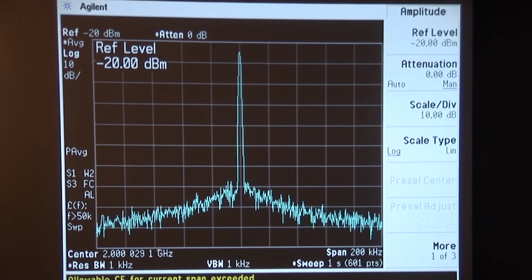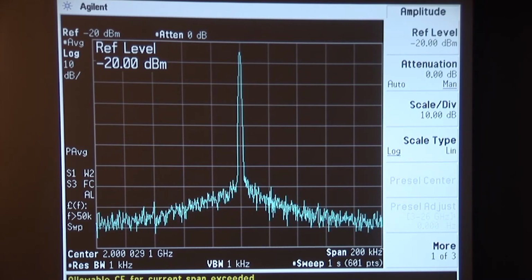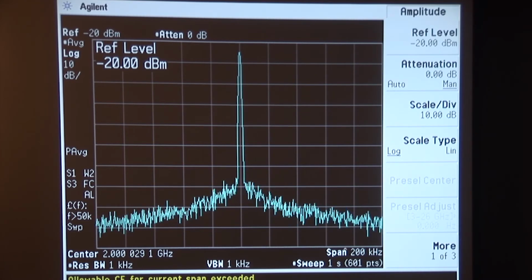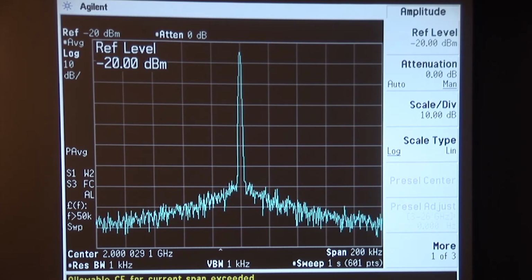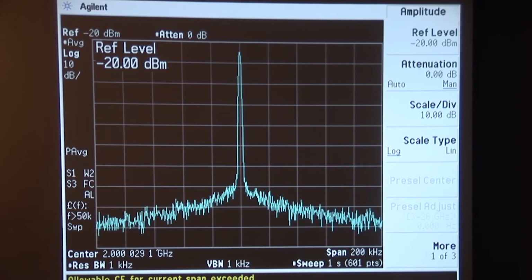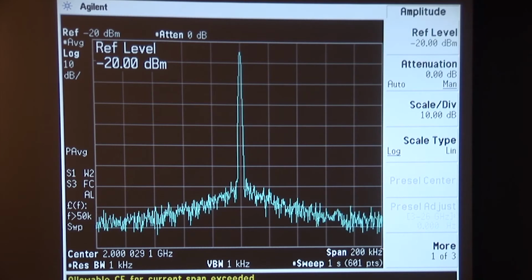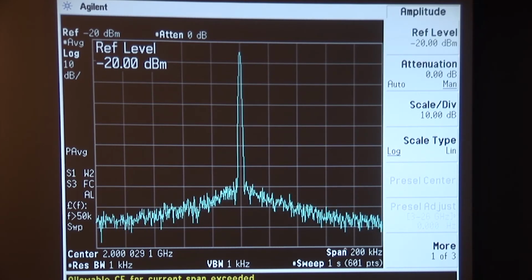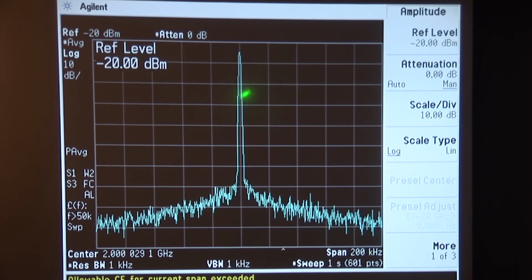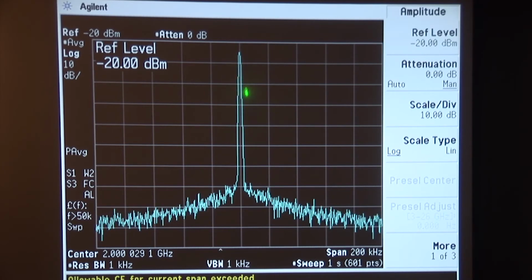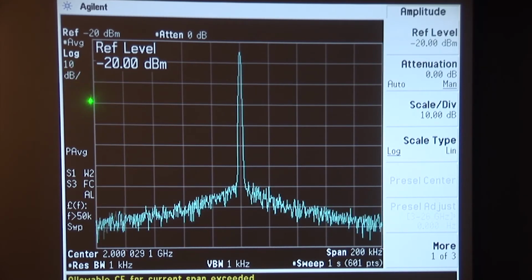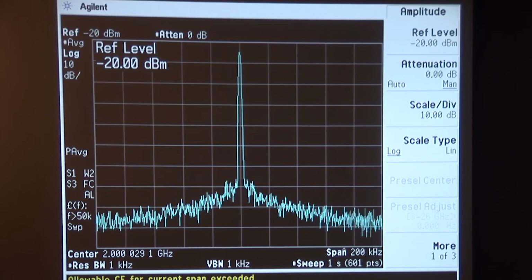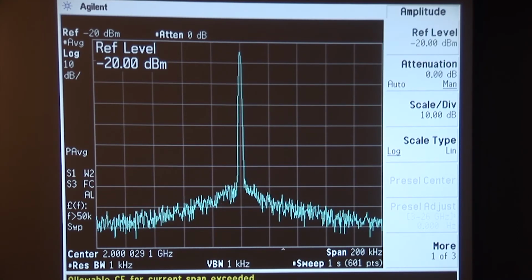a certain span, and we need to do the math to make sure that we're actually getting a convolution on the spectrum without gaps in the spectrum as we're moving what can be, in some cases, a relatively narrow IF filter across what can be a relatively wide frequency span. Let's just do an example right here, right now.